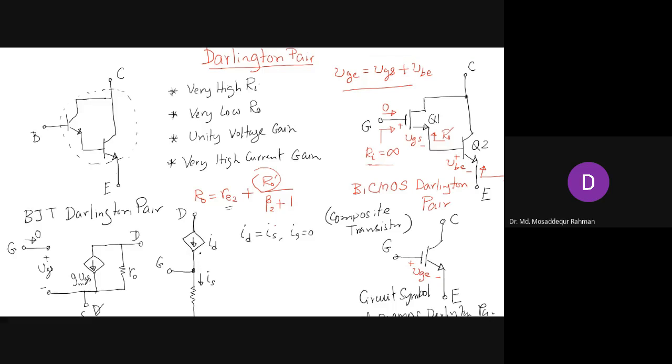This is the difference with the bipolar junction transistor, where IC is alpha IE. So there's a parameter alpha, but we don't have alpha here. So that's one difference. And here the resistance is given by 1 over gm. What we had for the transistor as re, we have gm between gate and source. Now, how do we get this gm? If we look at this model here, the pi model shows infinite, but in the T model, we see a resistance of 1 over gm.